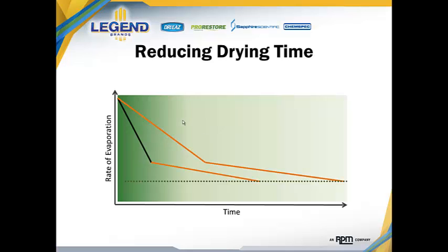If we progress again without making any adjustment or focus on the necessary components of humidity, airflow, and temperature, the drying rate again is going to be relatively slow. Now, if we started with good airflow, it's still going to be better than if we hadn't, but it's still going to be slower than it could be if we're leveraging humidity, airflow, and temperature appropriately. Properly leveraging the energy available on the project, however, is going to give us that overall best drying rate.